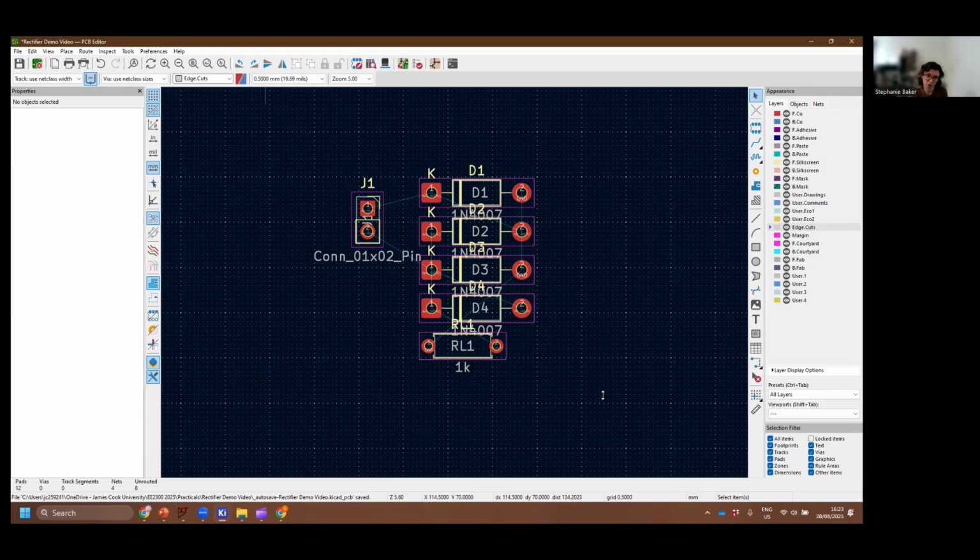So we want to make the board as small as we can so that we don't have to have as many tracks. And this is the same logic as when we build a breadboard, right? Like since first year, I've been saying, make sure you don't use more wires than you need to and everything else, because all of that introduces small amounts of extra electrical resistance and generally affects the signal integrity.